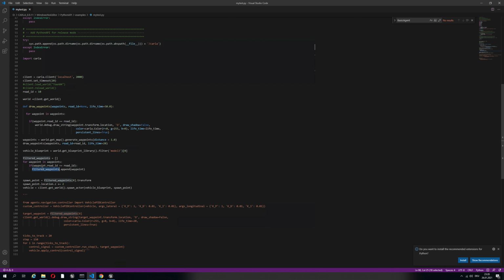to the list. And here we're saying, okay, take the first waypoint of that section of road ID 10 and spawn the vehicle on that waypoint with a bit of translation along the z-axis, say like 2 over, because otherwise the center or the origin of the vehicle would be exactly over the point, but you need to translate a bit up so it is on the road.